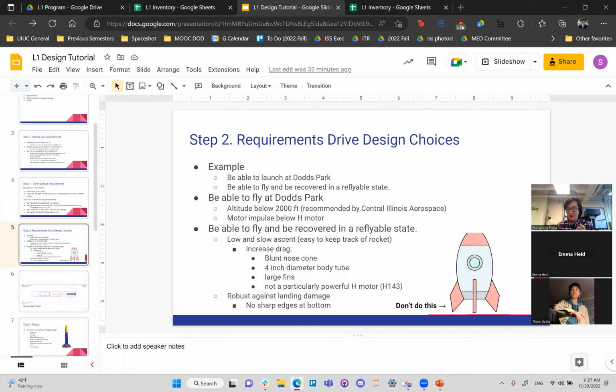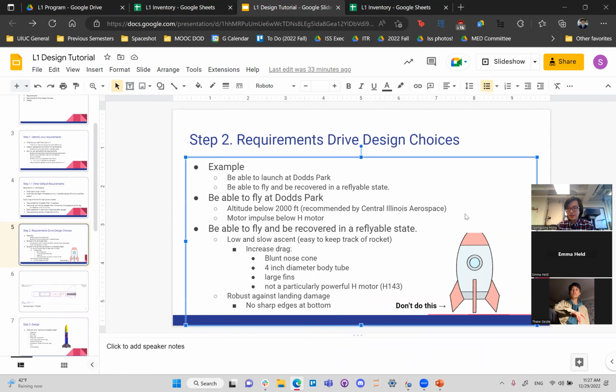Okay. But as for how the parachute comes out, do you remember A100? Yeah, I got a little confused on why we needed an altimeter. So I don't need one. I understand, it just pops out at apogee. Yeah, you have a small explosive charge at the end of the motor, and it pops everything out. For H class motors, all of them will come with the ejection charge.